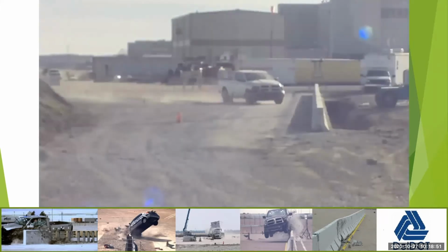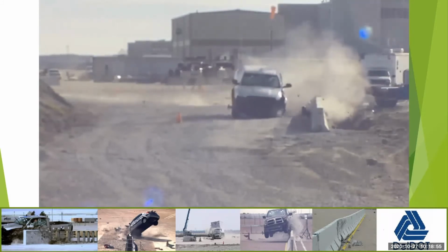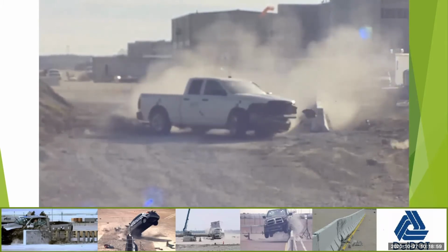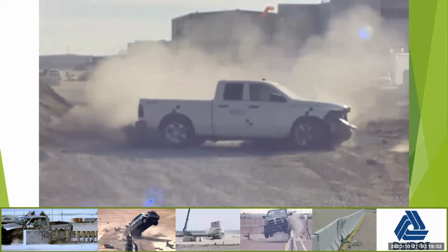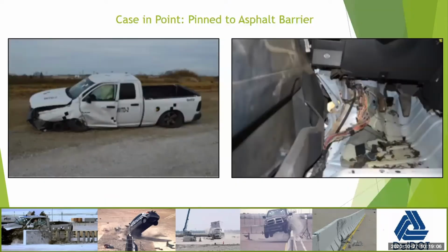This is the crash test for the MASH. So the truck's redirected, doesn't roll over, seems to contain it pretty well. Is this a passing test? And the answer is no. Under MASH, this is not a passing test. And the reason why is the wheel well deformation shown on the right side of the screen exceeds that 9-inch criteria. So go back to the NCHRP report 350 criteria, and this is a passing test.